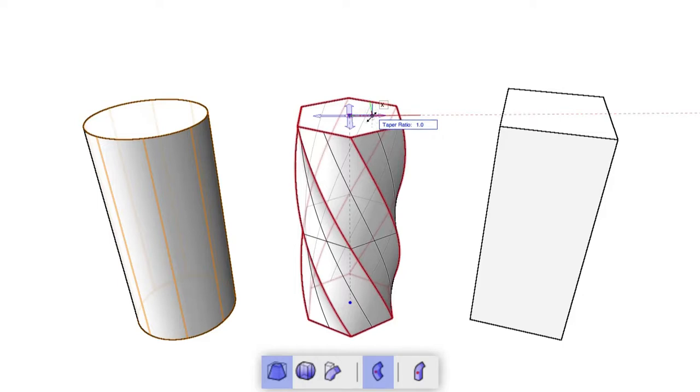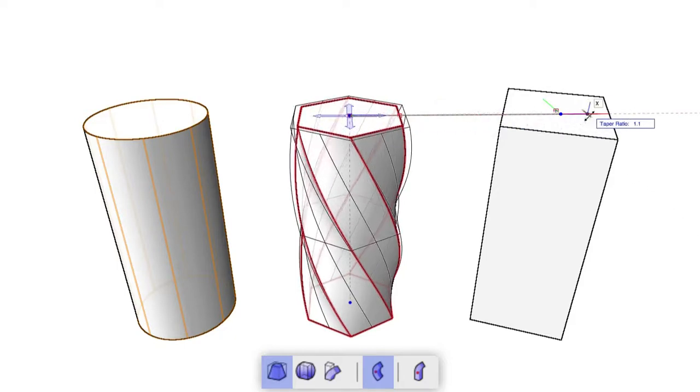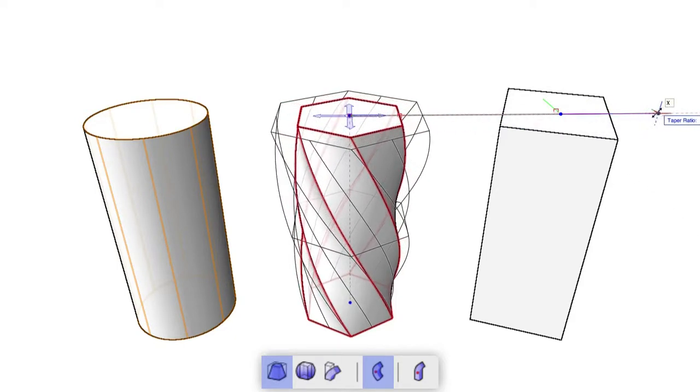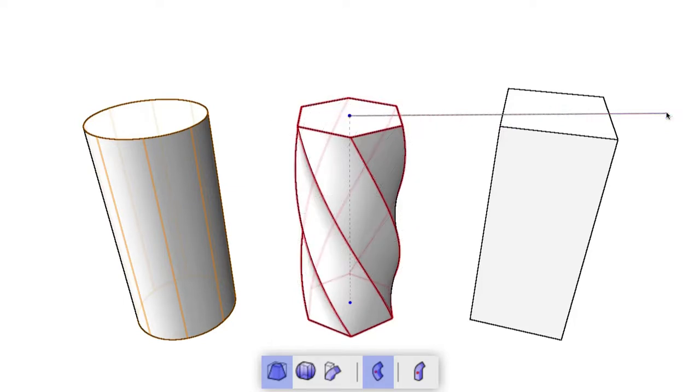If we perform this operation again, but this time set that second to last click far from the arrows, we see that we have much more granular control over how far the object is tapered. This line effectively sets where the minimum and maximum will be for the taper operation. If we drag past the end of that line, the taper will expand in the opposite direction.